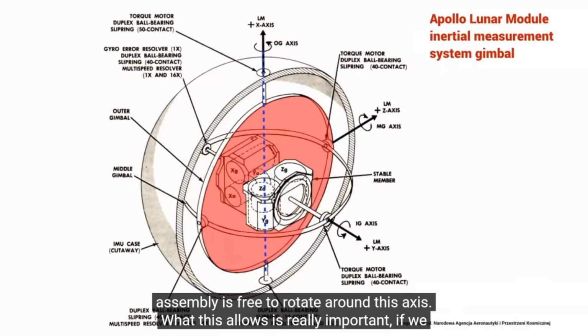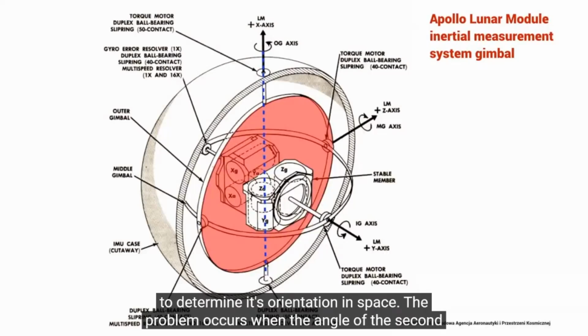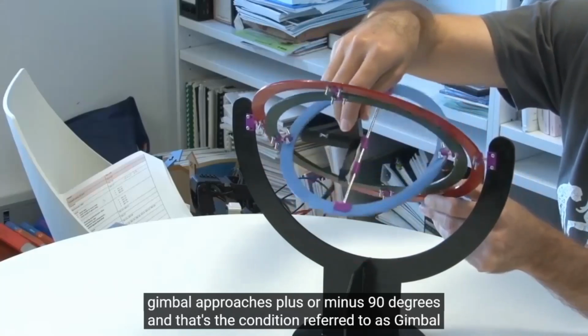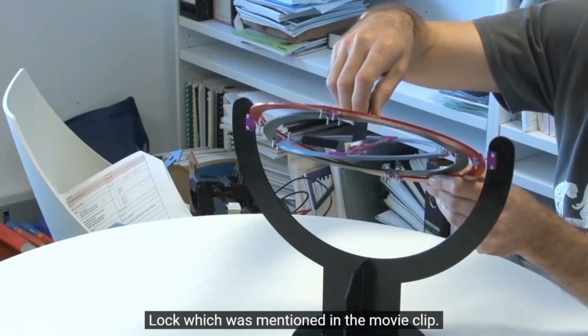What this allows is really important. If we measure the angles of the shafts in each of the gimbals, then that tells us the orientation of the vehicle with respect to the stable platform. And that's how this vehicle is able to determine its orientation in space. The problem occurs when the angle of the second gimbal approaches plus or minus 90 degrees, and that's the condition referred to as gimbal lock, which was mentioned in the movie clip.